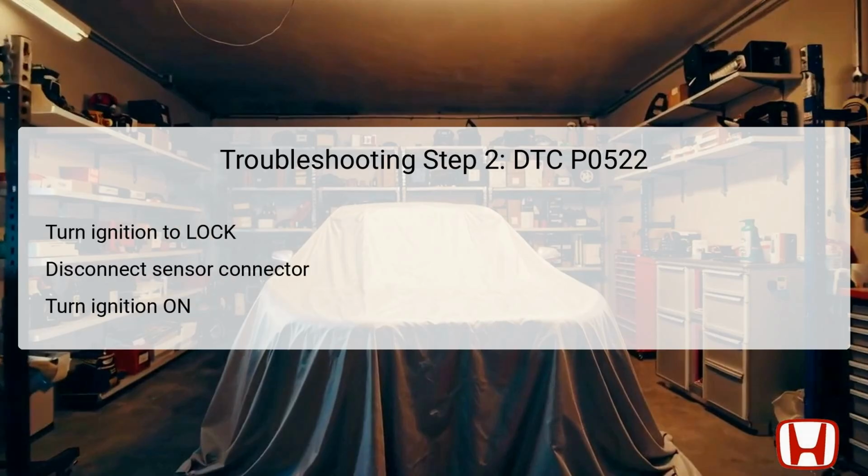In this step, you need to turn the ignition switch to the LOCK (0) position to reset the electrical system safely. Next, disconnect the 3P connector from the rocker arm oil pressure sensor to isolate it from the electrical circuit. Once disconnected, turn the ignition switch back to the ON (II) position again. This allows you to repeat the previous measurement of voltage from the disconnected sensor. The purpose of this test is to further confirm whether the sensor itself is the cause of the low voltage or if it's a broader wiring issue.